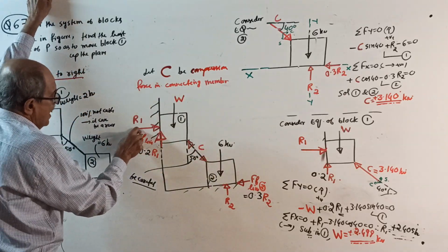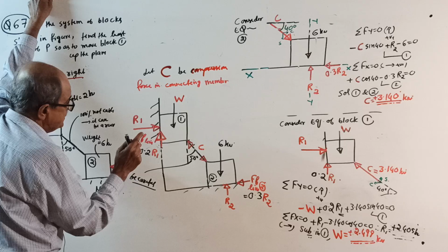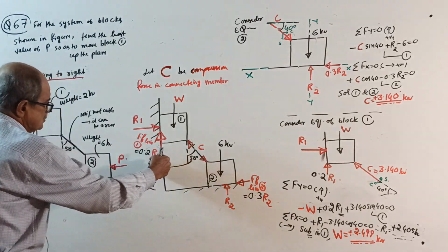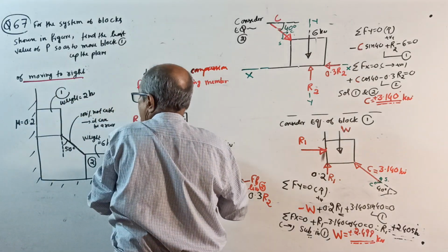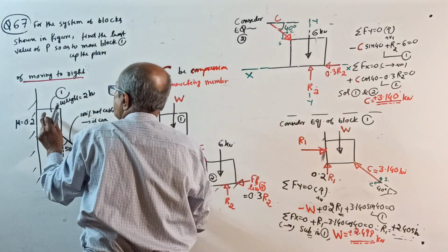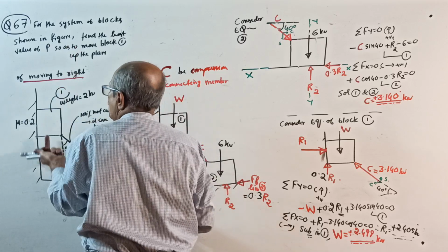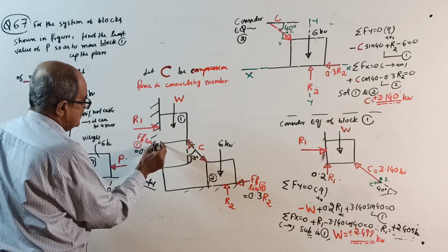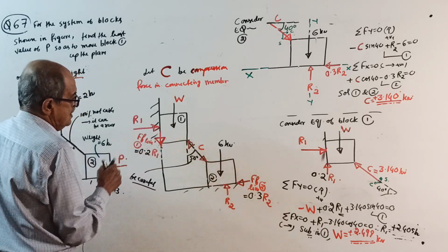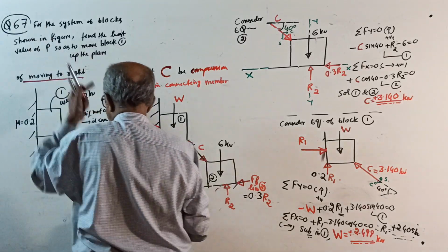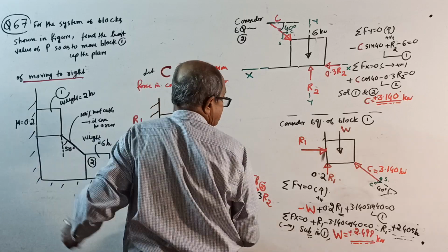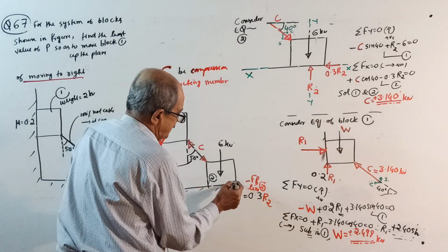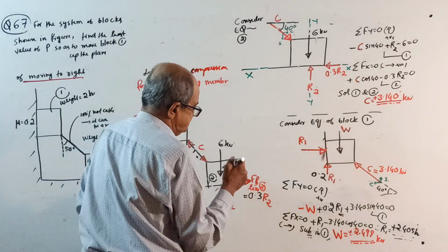Now, see R1, R2. Friction, be careful. Again make a note. When you apply the force P here, this block 1 will move up. When block 1 moves up, friction is down. You have to write this if you want. And when that is moving up, this will go to the left side. So friction is to the right side. That is important. This change will come.